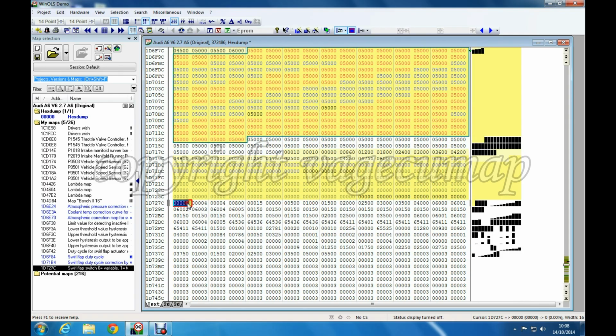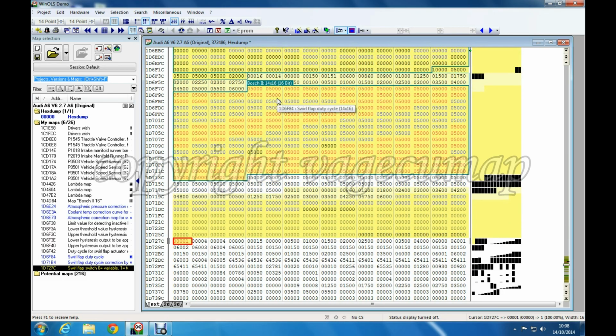If you change this to 1, 2, 3, 4, 1, enter, what you've now got is a 1 there, so you've changed the switch for this. And that 1 appears to tell the ECU that you are now not using these maps for variable function of swirl flaps. You simply have fitted to the car 2 position flaps. Now of course there's no such thing as 2 position flaps, but that seems to be what VW Audi call no flaps. So when there's no flaps fitted, they look at it as a 2 position system.